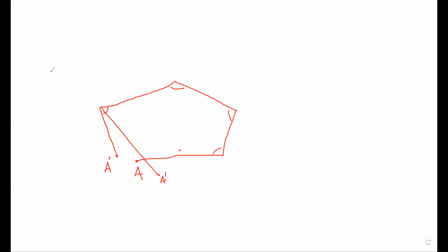Right? So we are discussing the graphical method. In the graphical method, I explained the first step is, without going for the drawing, before going for the drawing, you have to correct your angles. Still, you will not get a closed polygon because your lengths are also wrong. You have two sets of measurements, a set of angles and a set of lengths. Both contain errors. Clear? So the first step is correcting the angles.